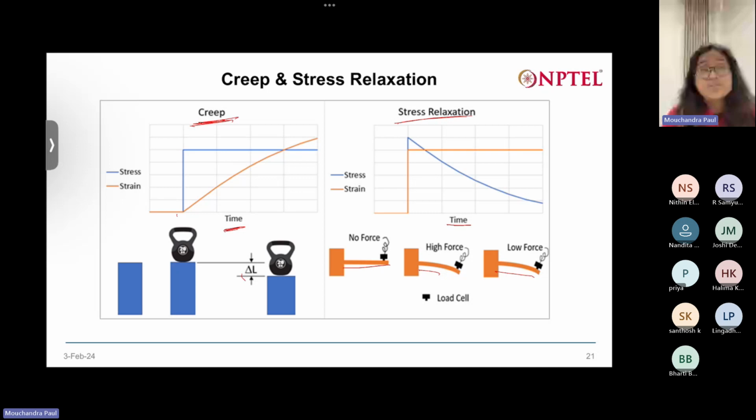Polymer has become a very important class of material when you make an artificial tissue to mimic the property of the inherent organ or tissue in our body. When explaining its mechanical properties, you can't rely just on elastic properties; you have to go towards viscoelastic properties as well, and understand how creep or stress relaxation is happening in it.